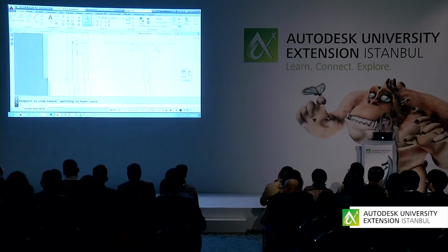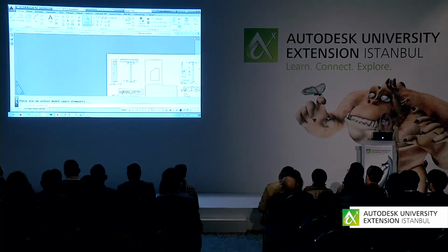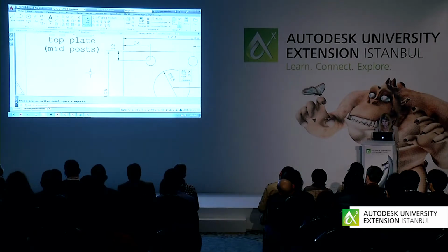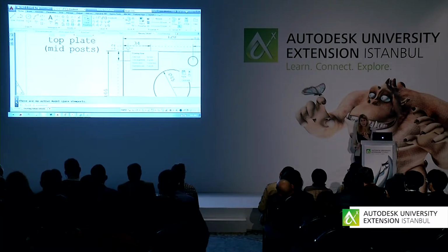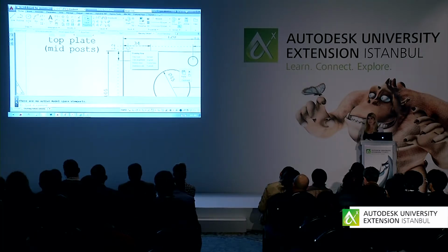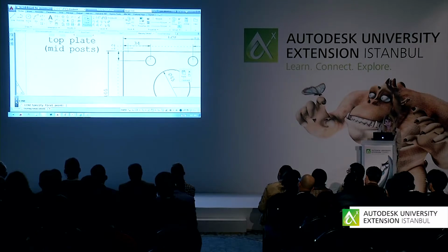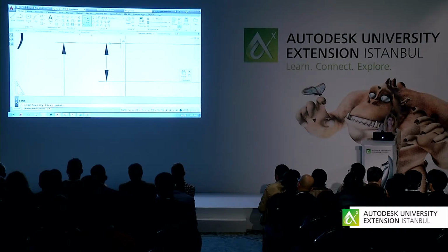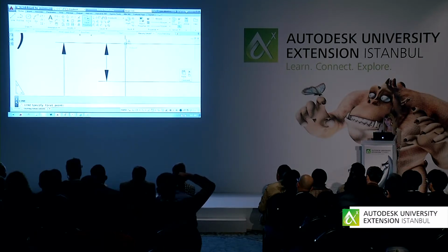You will also see, by default, AutoCAD will no longer recognize the endpoint of an extension line as an object. If you've ever tried to grab the corner of an object and it accidentally grabbed the dimension instead, that won't happen anymore. Let me show you what I'm talking about. I'm going to go on the line command, and you'll see that it will not allow me to grab the endpoint of the extension line, only the object. If for some reason you don't like that, you can turn it off as well, but I think it's a big time saver.